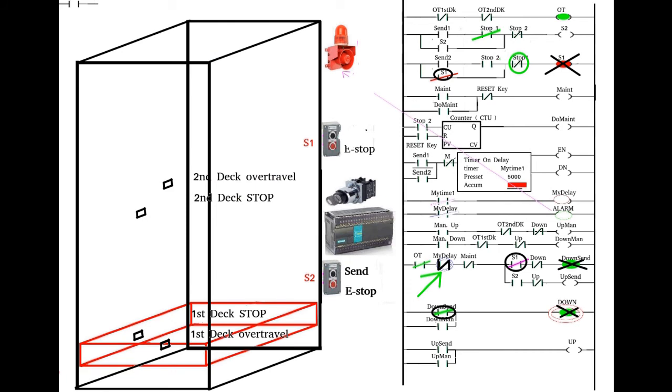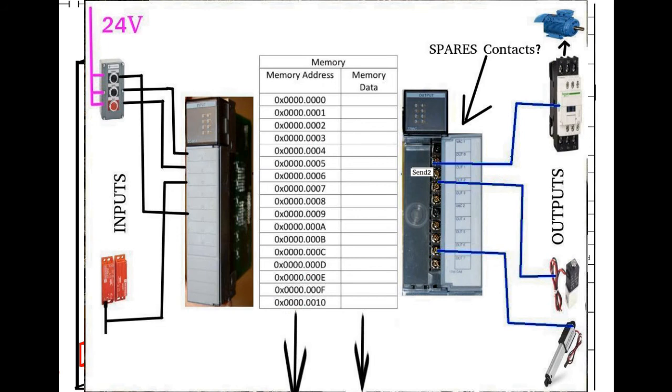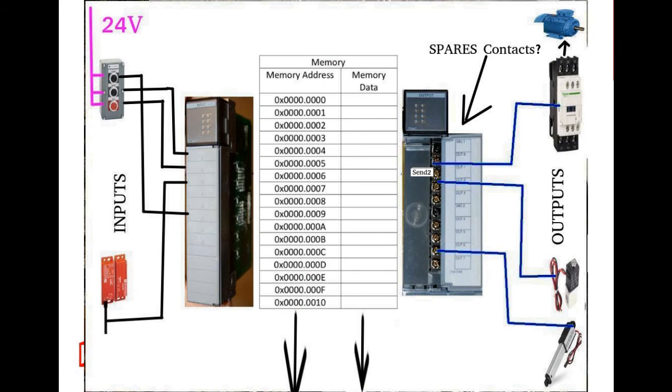I would like to add that if you have spare contacts on your output module, for example, you cannot just simply switch to them, because when they write the program, they define which ladder logic outputs are going to correspond to particular output module contacts. Some of the more advanced PLCs let you do that, but you still need to have permission.